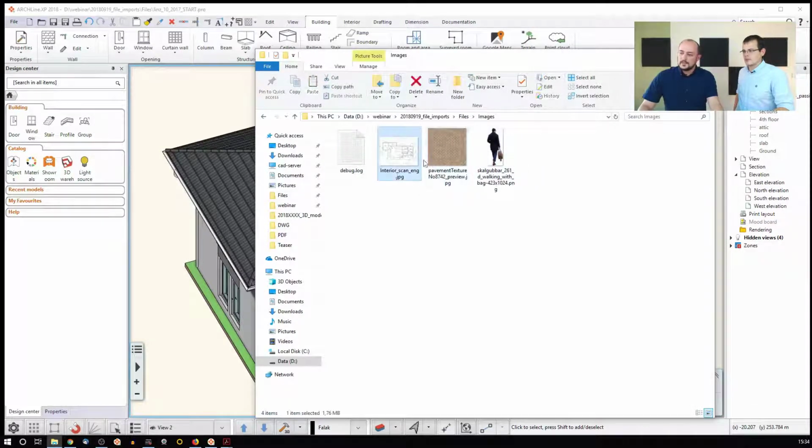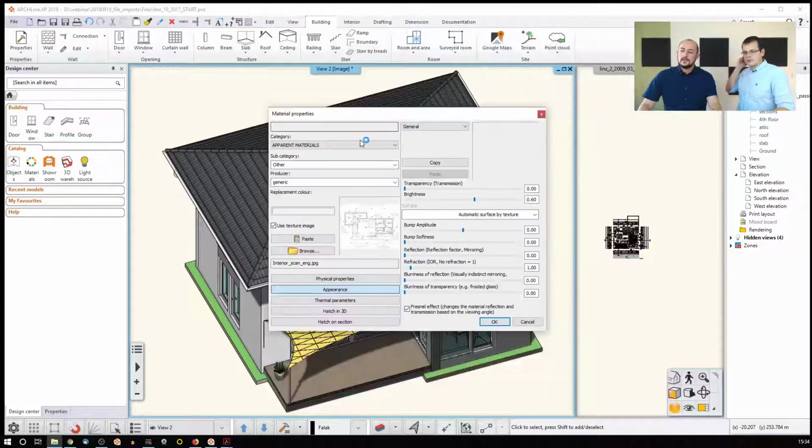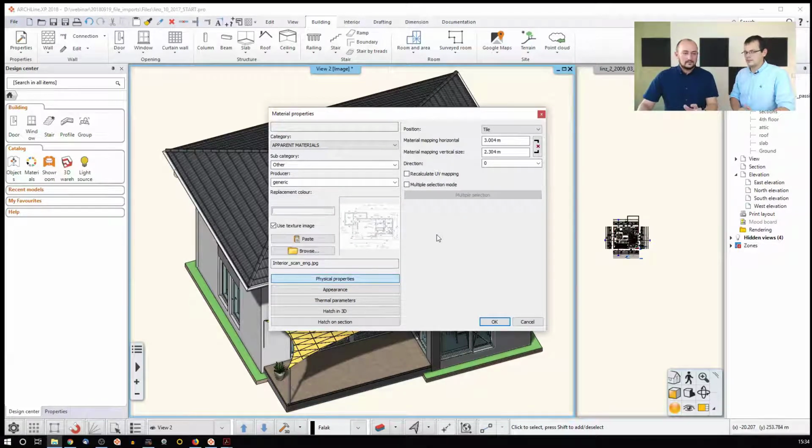Not all of them are textures, but let's just select this and this, click and drag and release it over here, and then the software will give me the opportunity to save all of them with the same settings, with the same size. This comes in handy when you have specific fabric patterns of the same type and you would like to quickly do the generic settings and then fine tune them one by one. So you can click and drag and import multiple image files and turn them into materials in one single step.